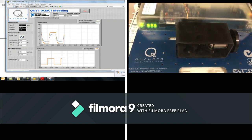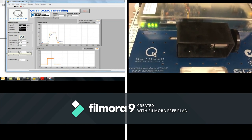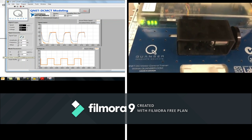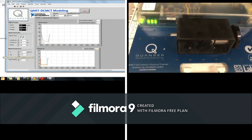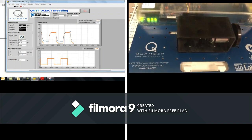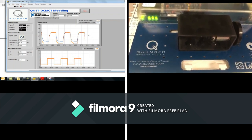So here now for validation, I'm just increasing the value of K a little bit. Okay, a little bit more than that. Okay, it seems matching right now. What about tau? Tau controls the x-axis, the time axis. So if I reduce this, let's see. Okay, it seems good. If I reduce this, still okay. That seems good. So the rising is perfectly matching, and now I'm done with the modeling.